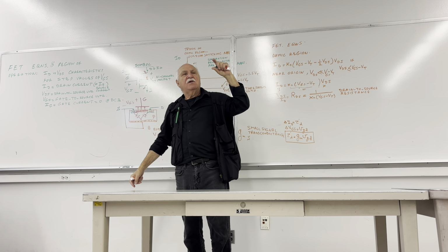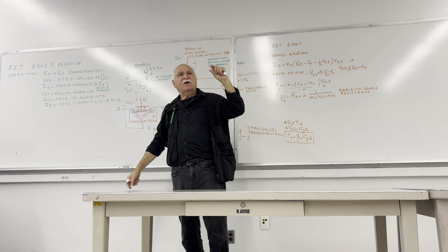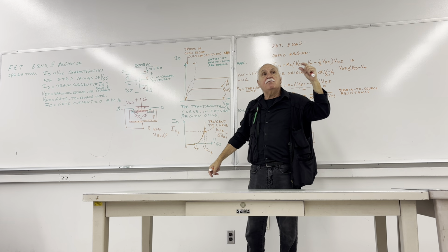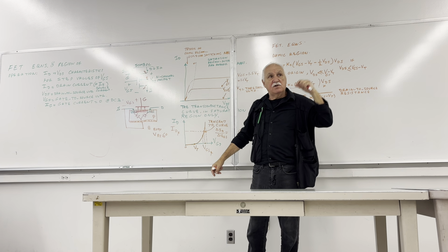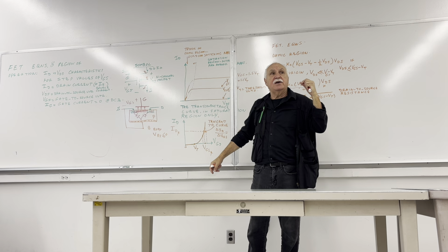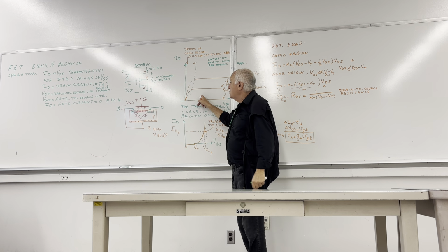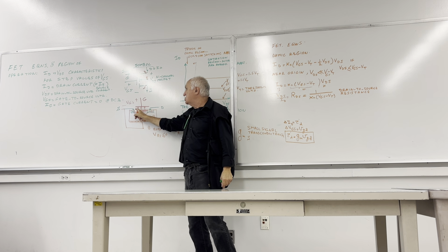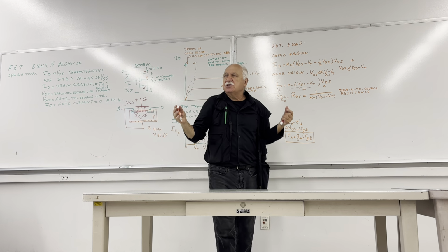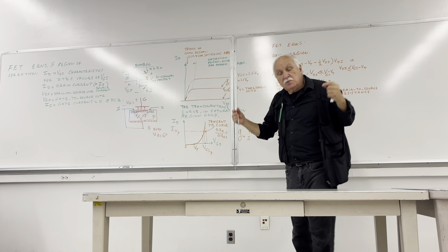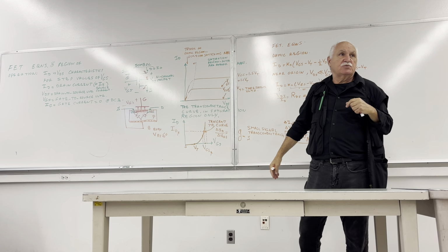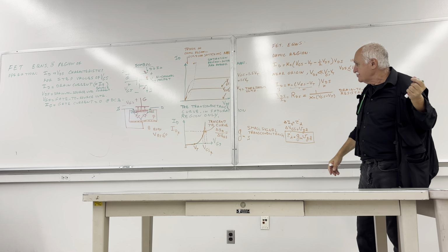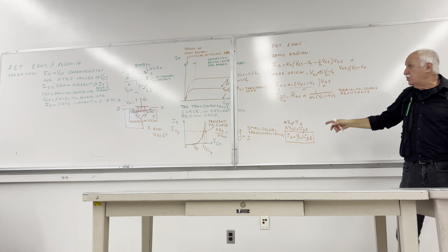So if you are putting 5 volt across 5 micrometers, your electric field is 1 megavolt per meter. 1 megavolt per meter is a seriously high electric field, so high that it might even break down the insulation. The insulation can resist only so much electric field. So there is a limit on the gate to source voltage as a result. You can't put arbitrarily whatever you like. There is a maximum you can put.